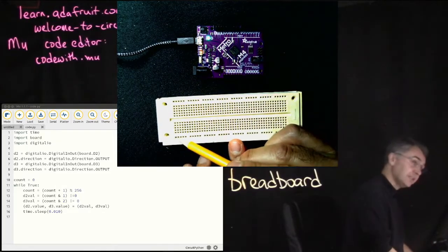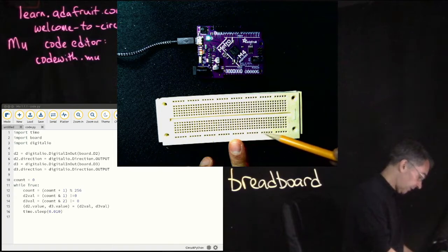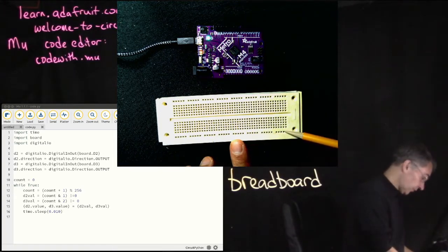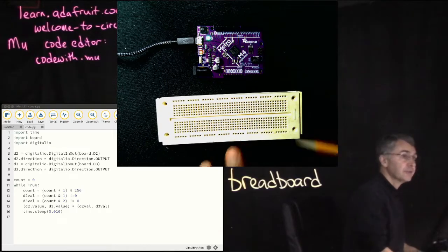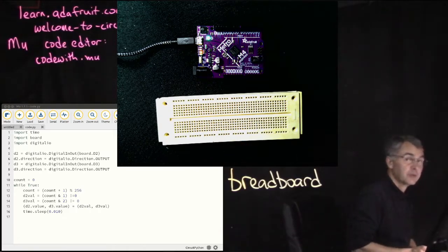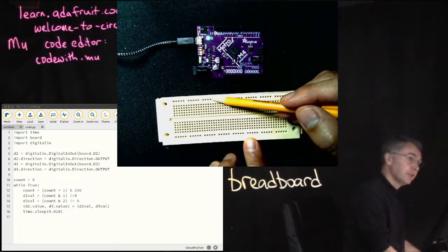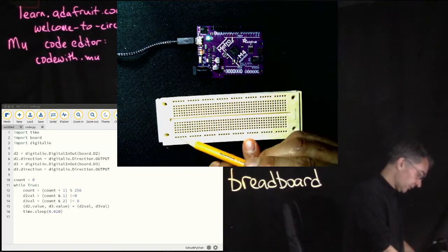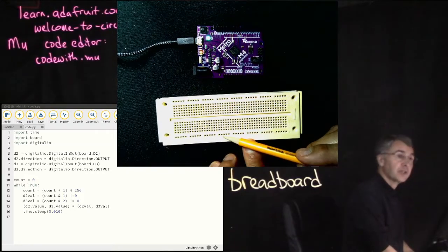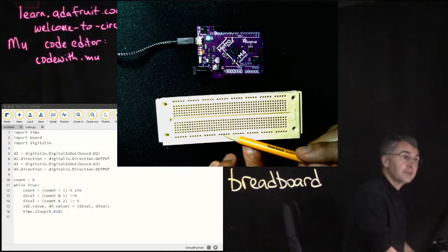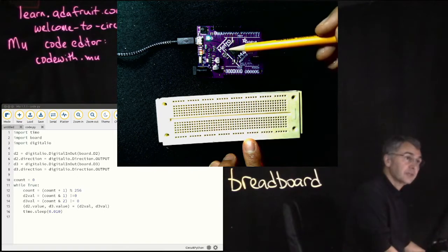If I plug something in here, it's connected to anything else on this big bottom row. That's usually useful for things that want to connect many places, which turn out to be often two places in our circuit called power and ground. So in our case, this might sometimes be 3.3 volts, and this will usually be the ground pin, which serves as the reference voltage for pins going into or out of this M4 board.